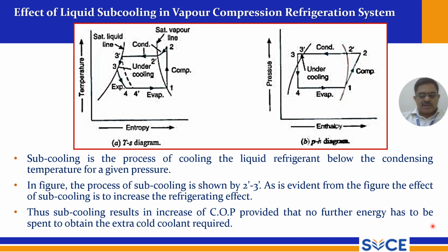So that is very important. No energy should be wasted to obtain the extra cold effect. So that is the subcooling process advantage. When you are applying this, there will be an increase in COP. That is a desirable characteristic we are getting out of this.